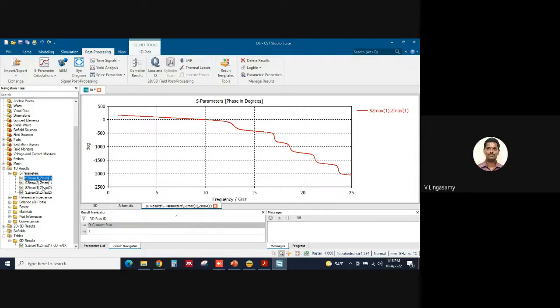Low dielectric constant substrates, and also thicker substrates. But at the same time, you will lose gain as well. So it is a compromise between gain and bandwidth, right? The gain-bandwidth product is constant. That is why we have to play with the thickness, but the thickness should be standardly available. It comes in ounces, right? Multiples of 0.035, like 2, 3, 5. So multiples of an ounce will be there. We have to check whether it is easily available or not.